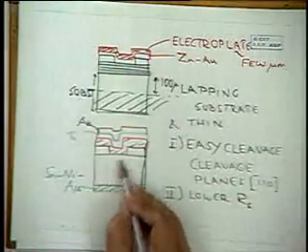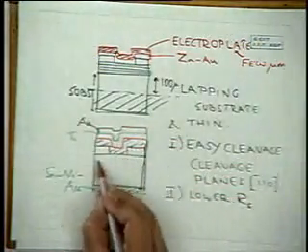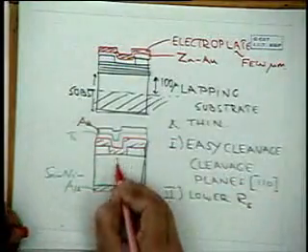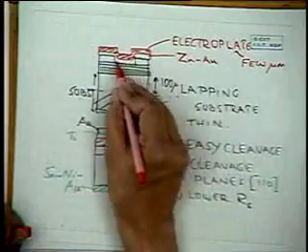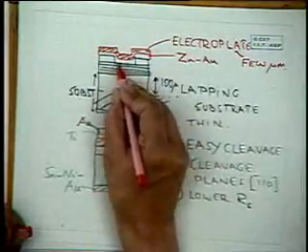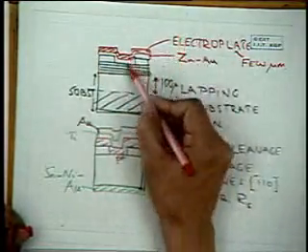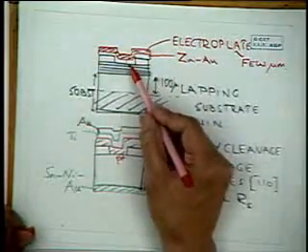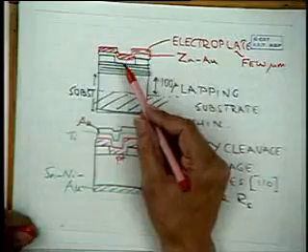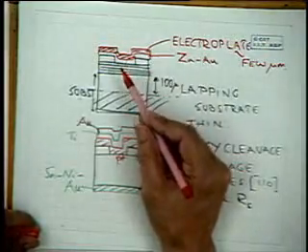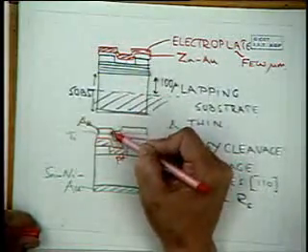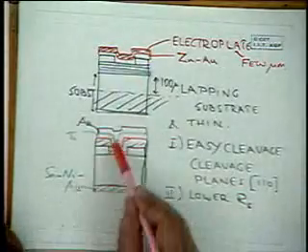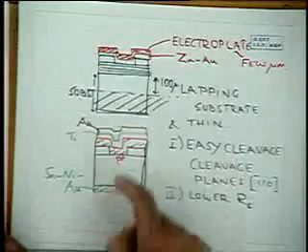Why do you have to take a lot of care on this p-type side? The reason is, of course, that with this geometry, this area being very limited, the series resistance builds up. It is much more here than here. And of course, ohmic contacts to p-type materials are intrinsically more difficult than ohmic contacts to n-type materials. So you have to take all the trouble of making very low series resistance contacts to this.